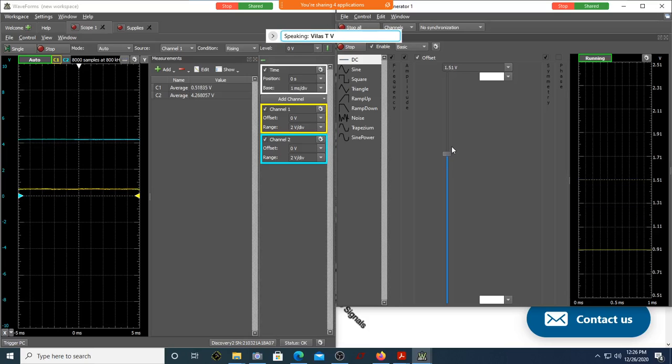Shall I vary this, make it more and more? Is your output voltage changing? Is it the same there? See the output. This is because it is changing only in terms of tens of millivolts, which is negligible. So it is plus V set. Correct? Keep on increasing. Can you see, is it plus V set? Does it mean to say any voltage greater than 0, you have it as plus V set?